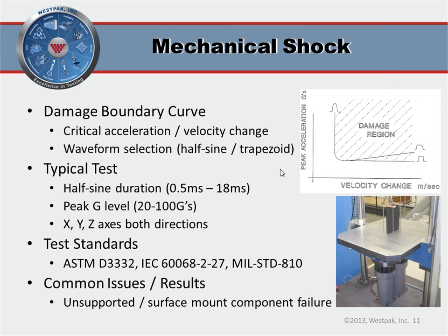For several reasons. One, it's very common in the environment. We measure it a lot. It's very easy to generate in the laboratory as well. Elastomeric materials or a variety of different materials are used to generate that shock pulse. And the materials are simply placed between the platen where the product is mounted and its impact surface.